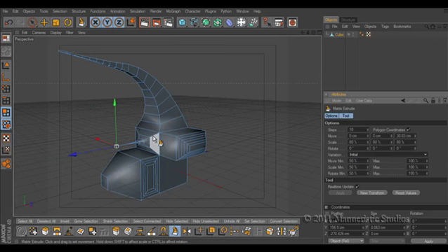Okay, you see that the scale goes in to initial as it goes from the start and then thins out to a point. We can also go into per step, and you see that it's still a lot smaller than when we say none, so it's more control. So if you want more control, you use per step, or if you want this effect, just the initial first 2 polygons that are actually generated from the 10 steps, for example, you would go into initial.